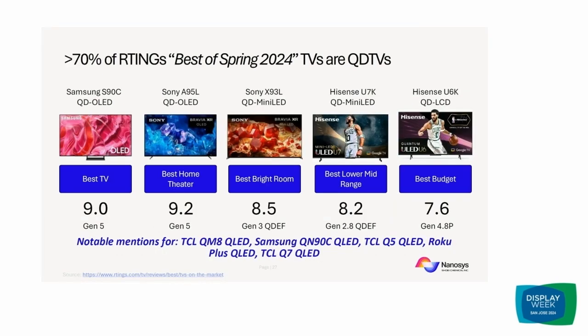These are multiple different brands that are out there, multiple different types of quantum dot displays that implement quantum dots. So it's not just QDEF anymore that's out there. And it's also different material types. So it's indium phosphide, it's cadmium selenide, and blends of the two of those.